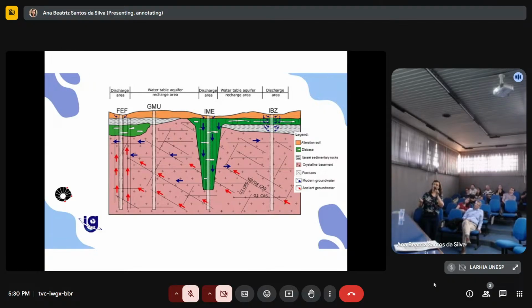Here in this well, which is our focus, I will talk about it later on. We also have a mixture of old water and new water. And here at Fifth well, we have mainly old water, and the flux is upward. The specific capacity of this well is really, really good. You have a good yield, but you have practically no lowering of the water table. So this is what we concluded from all that we did.